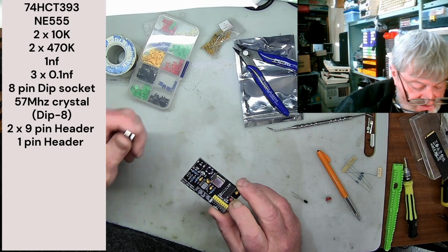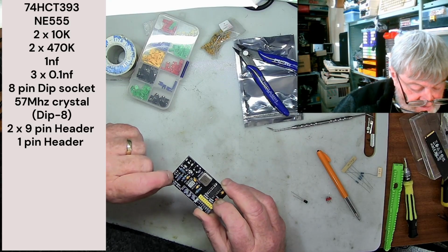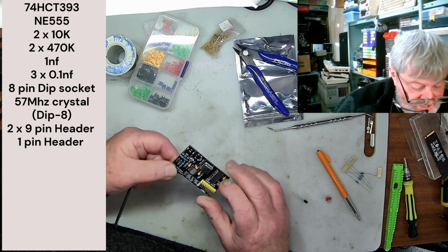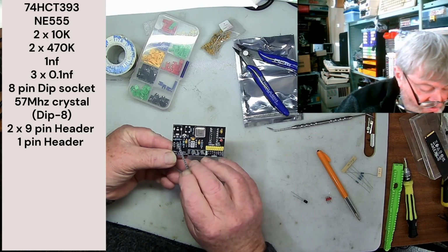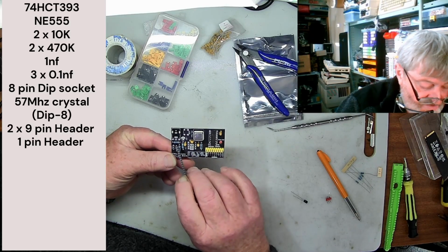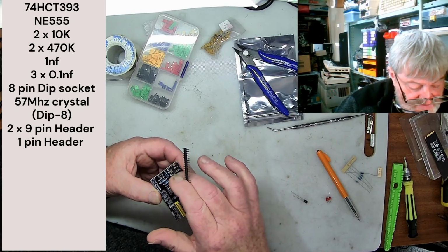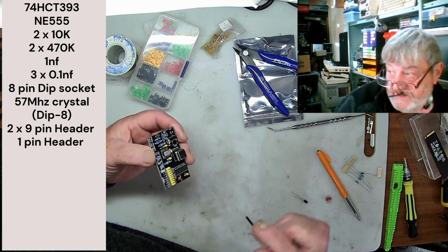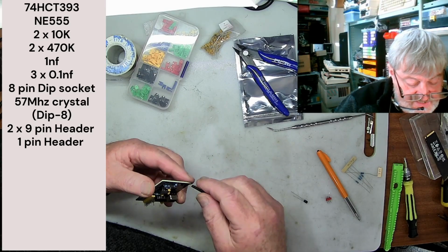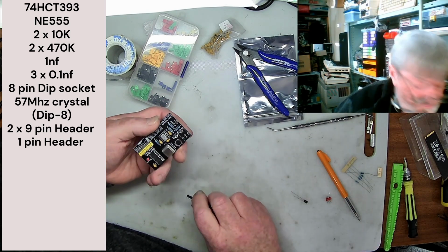The only thing I'm missing off here is the reset, which goes between this resistor and the transistor here, but I could always tag a pin off up over here to solder onto that resistor. That'll give me the reset line, and for a ground off the side of the earthing on this, I can actually put a pin underneath here, get a right angle one for a ground if I need to.